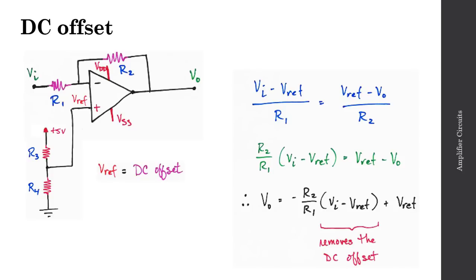So if I had something like a DC offset of maybe 3 volts, this would effectively shift the entire voltage down, and then that AC component would now see the overall gain associated with R2 divided by R1, and since we're connected to the inverting input, everything will be inverted in terms of sign. Now, in the end, that reference, that DC offset, is ultimately added back into my output, but in this example, it's the AC component of interest that's getting amplified.